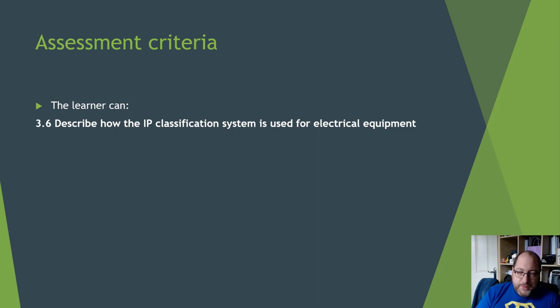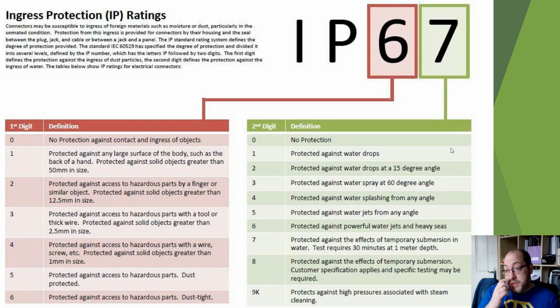Have a little revise on those. IP2X, IP4X are the common ones for protection against barriers and obstacles in 416. But I would say also think about the external influences from special locations. You know, swimming pools will be down to IPX8 or IPX7. You've got things like saunas and stuff. So have a good understanding of how the wiring regulations reflect changes in IP ratings, minimum IP rating for outside lighting, things like that, and then that should be sufficient. That should be sufficient.